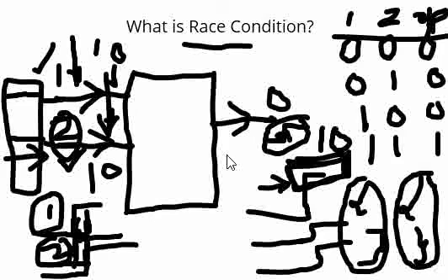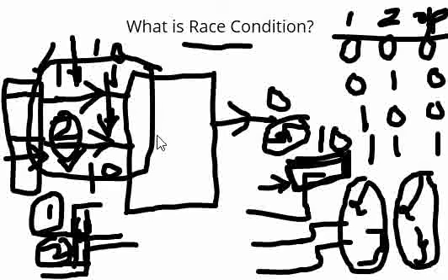Now, commonly the scenario which we see with the indicated case is a dynamic race condition, where the transition timing difference between two signals transitioning to different states at the input of a particular IC is a dynamic race condition.